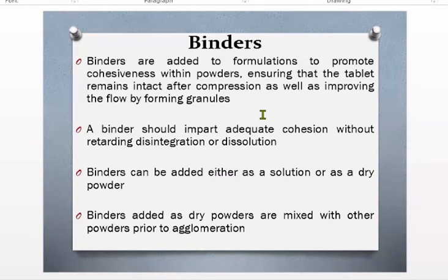Lawrence was asking earlier about the possibility of powders not being able to stick to one another. So the selection of the binder is important, and also the concentration of the binder that you are using. That will dictate the strength of cohesion that exists between powders once you compress them.